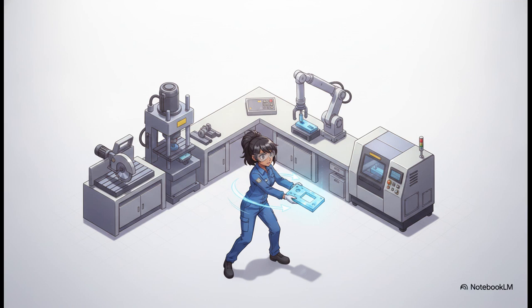The fundamental goal of a lean work cell is to remove absolutely all non-value-added physical movement. By organizing the sequential stations into a tight U, the physical ergonomics for the worker improve dramatically. I mean, instead of walking 20 feet down a long, straight assembly line to hand off a part, an employee working inside a U-cell can finish an operation, simply turn 180 degrees on their heel, and place the workpiece at the very next station. Turning is drastically faster than walking, and it immensely reduces physical exhaustion by the end of a shift. Plus, it entirely eliminates the need to constantly pile up and transport large batches of inventory.